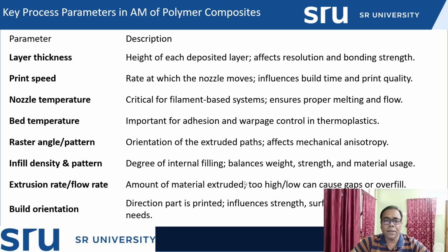Similarly, coming to the other parameter, that includes the bed temperature. Sometimes if the proper bed temperature is not given, in that case what happens, whatever material is coming out from the nozzle will be deposited on the build platform. If the build platform temperature is not uniform, there will be chances of the warping phenomenon or maybe some adhesion related issue will come.